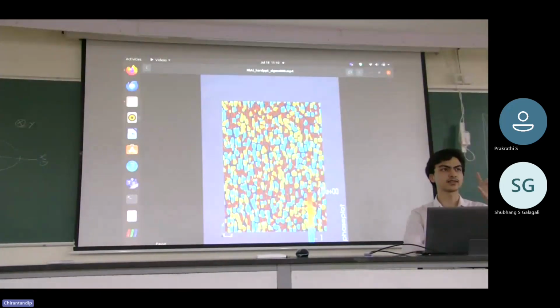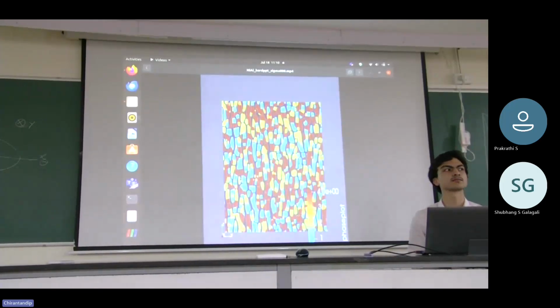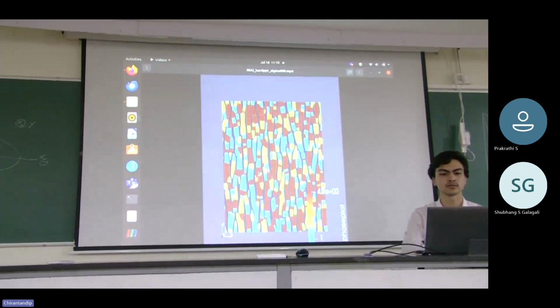So there are boundary conditions for boundary stresses available with the elastic solver. In the previous elastic solver that we had in the GP module, we did not have applied stress effects. Here now you have applied stress effects. So now you can do rafting. Applied stress means you give a displacement. So you find the effective displacement for having that applied stress, and you impose that strain, and then solve it. Loaded system. So the entire RVE is seeing the applied stress homogeneously.